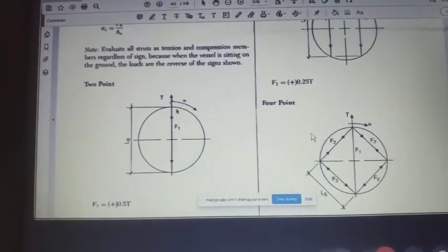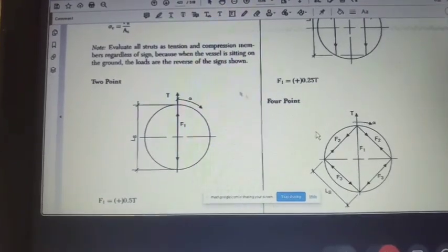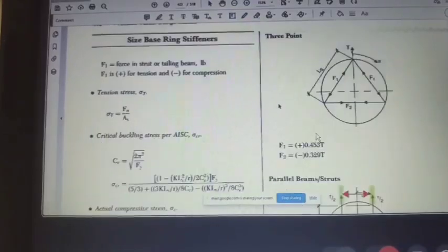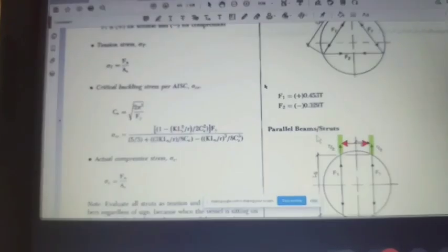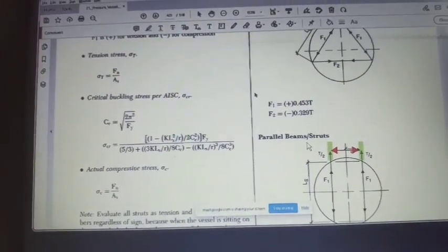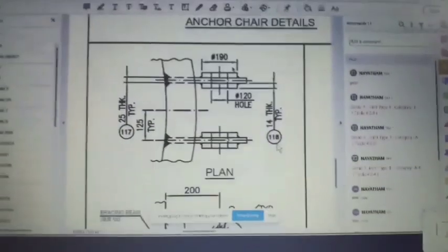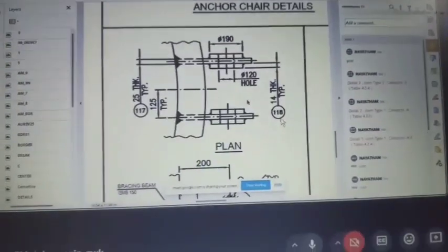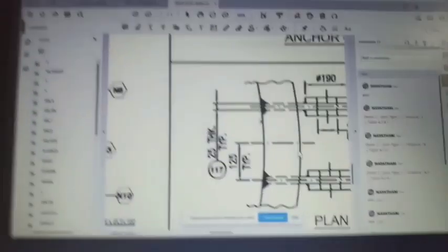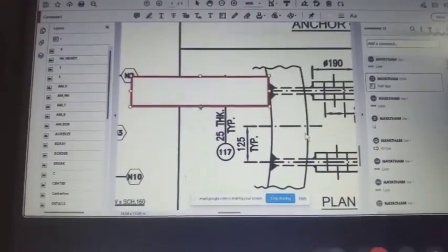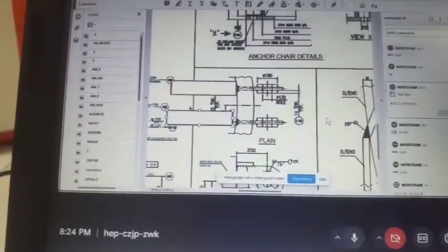So I think the 2 members will not fit. What is the weight of the equipment? Weight is around 60 tons. 60 tons. And what is the diameter? Diameter is 3.5 meters. So why a 250 mm distance? It's already given, they have already welded. Have you found the required member size as per this? No, I'm just going to do it, and I can find the member size once this is done. I tried with this, but it is not passing the calculation with the available moment of inertia. So I need to go for some other type.